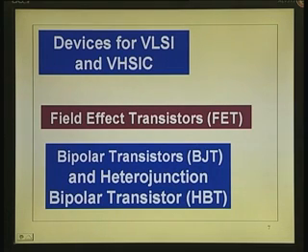All that you need to do is make the emitter region have a wider band gap compared to the base region. So, there you will have silicon germanium base, silicon emitter, because after all you know that the germanium band gap is smaller than that of silicon. So, silicon germanium will be somewhere in between. So that is the base. So, HBT, we will have ample occasion to discuss these things during this course.